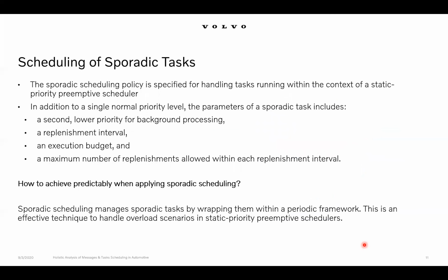The interesting thing with scheduling an event-based system is that when we look at the POSIX standard, there is a sporadic scheduling approach, based on the sporadic server approach, which makes the sporadic task behave as periodic by assigning a replenish interval to the sporadic task, which acts as a period, so that we can analyze the system and don't lose the predictability of the system.